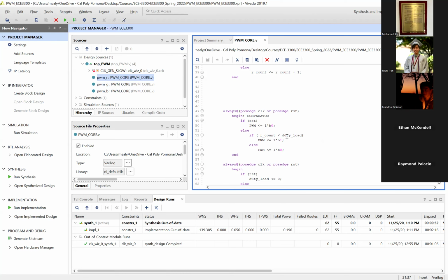Some sensors need the duty cycle to be 1 millisecond, but maybe the off will be 14 milliseconds. Maybe another sensor wants the on to be 20 milliseconds and the off maybe 1 millisecond. So the clock is supposed to be a special case of the PWM.